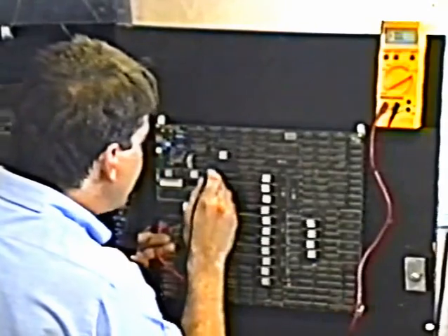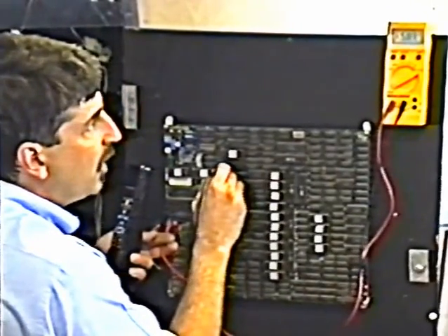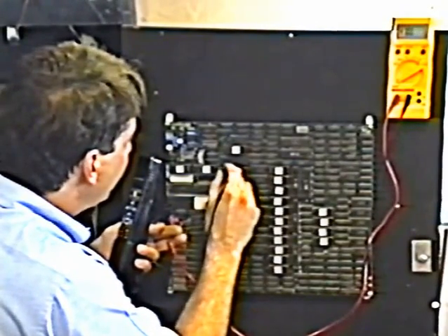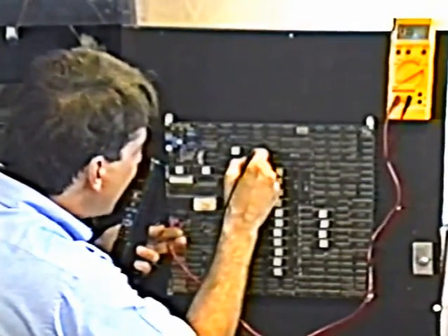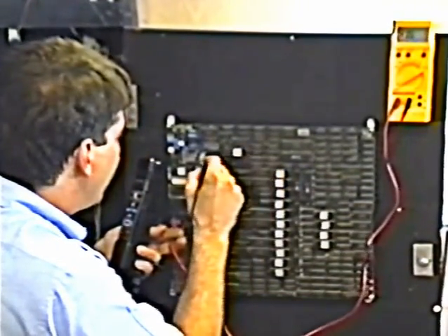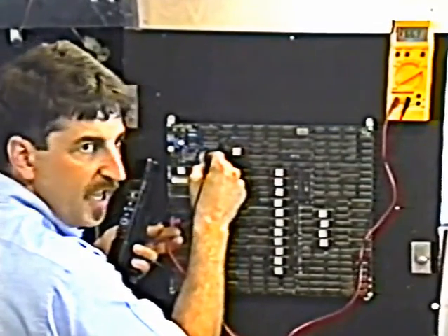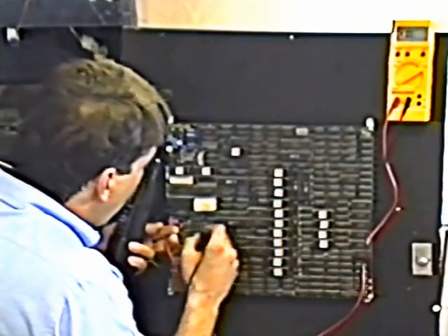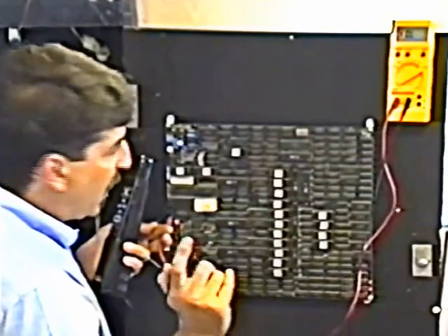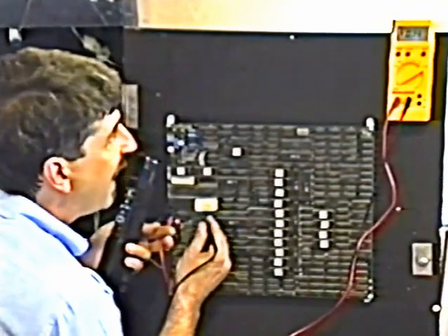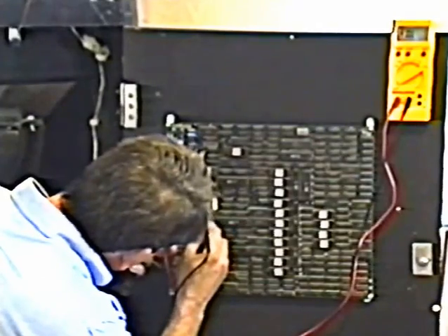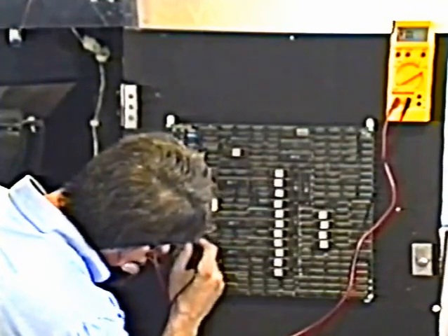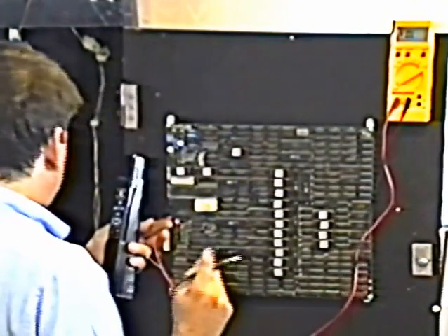When you probe the pins of the integrated circuit, you see a junction drop. Like now the meter says 0.5. 0.5. No matter where I go, I'm going all over the place, and I don't even know what these pins do. 0.5. I've got no idea what these pins really do. 0.6. Do you see how they're all checking like transistors? When you get to the bad one, you're going to see something a whole lot lower. Maybe something like that. Or, well, here, let me see if I can find a better one here. That's a dead short. It wouldn't be that bad. What am I doing wrong?